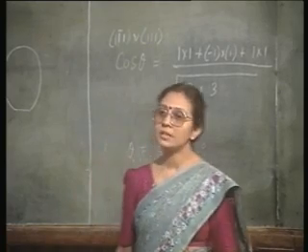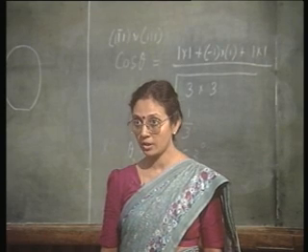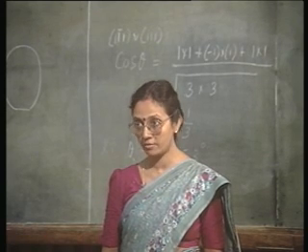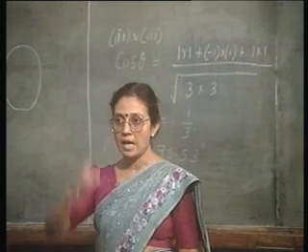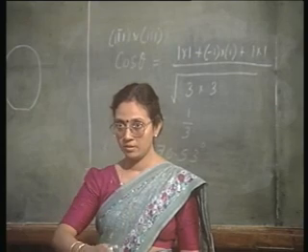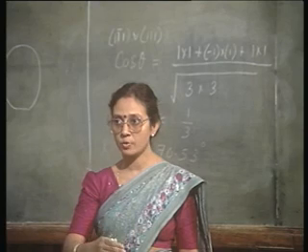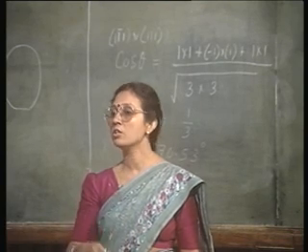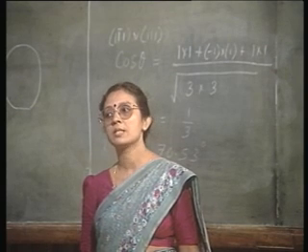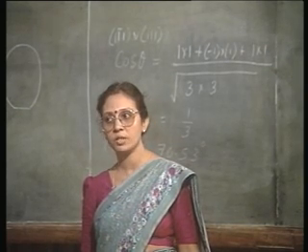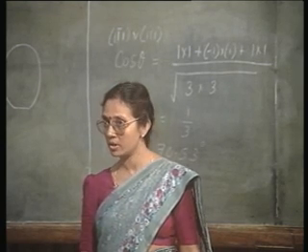Okay. So, theta is different. Notice that even here it is not really vertical, it is not 90 degrees, it is 70.53 degrees. So, whenever you cleave a silicon, you do not really have a vertical block. It is always the bulk plane that you are exposing, it is always making a non 90 degree angle with the surface. If the surface is 100, this angle is going to be 54.74 degrees. If the surface is 111, it is going to make an angle of 70.53 degrees.